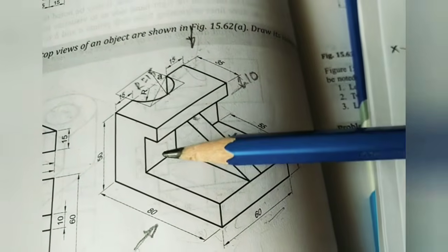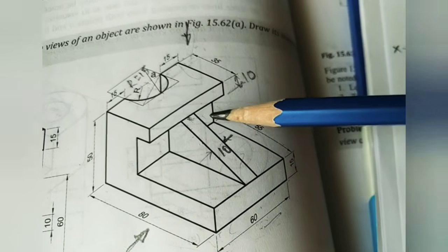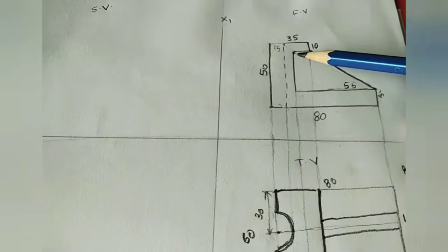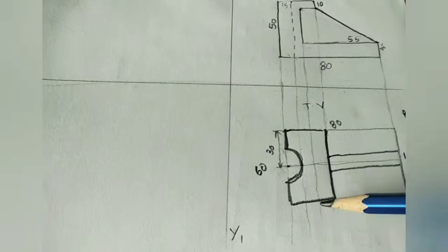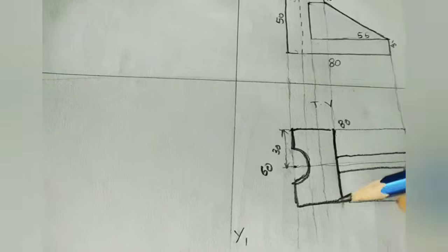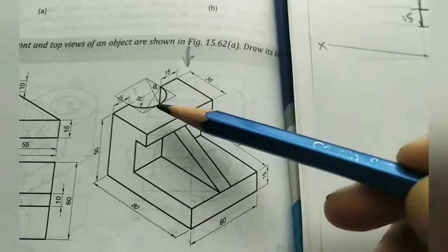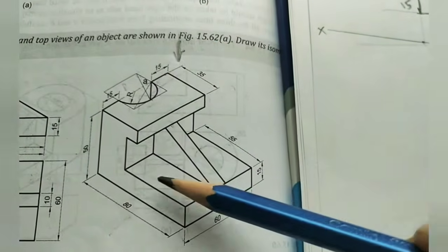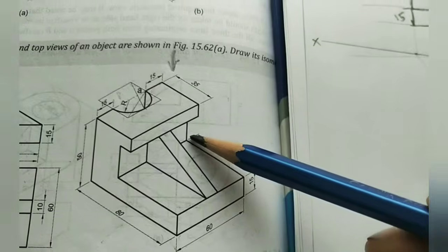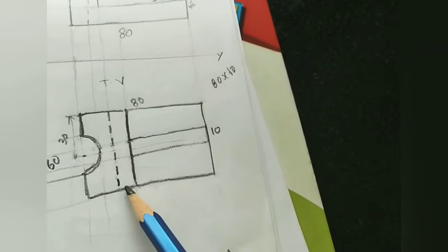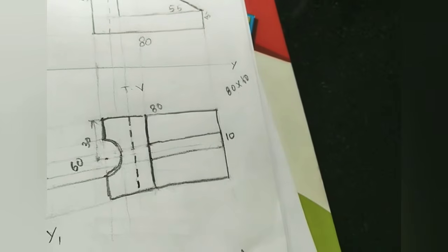From the top we can't see this hidden gap. From the top we can't see this. There we have to do the dashed line. Already from the top view we took this, so this part we can't see from the top. So wherever the projection line is there, we have to take it as a hidden line, dotted line, dashed line. After this semicircle, from the top view we can see this border also. The entire border, so in the top view, make this border dark. Already I did dark color. So this is the complete top view.